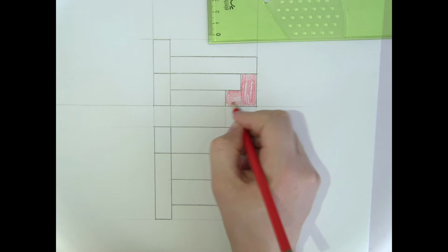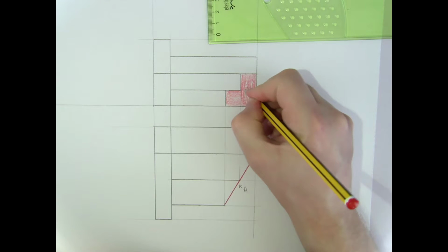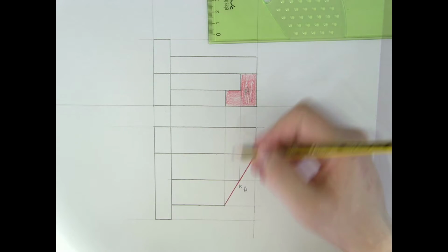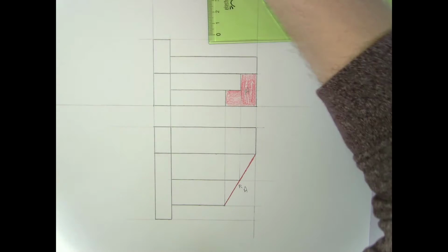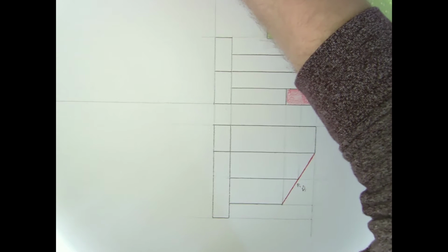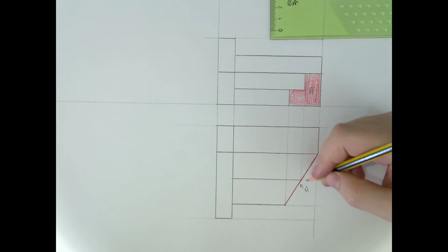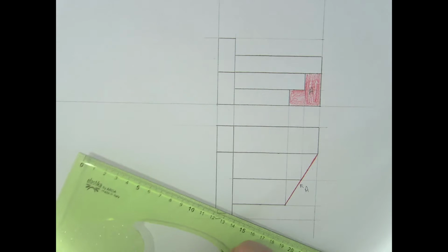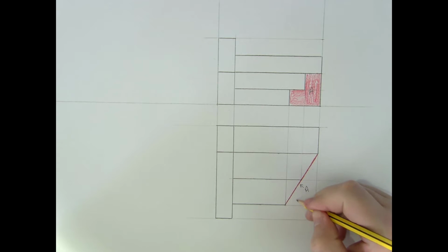But in our auxiliary, it's the true shape of the structure, so it's the whole thing that we need to draw the true shape of. So that's surface A, and this is an edge view of surface A. So for the next part of this, we're going to look at drawing the auxiliary view. And the auxiliary view is projected. To find an auxiliary, you need to look in perpendicular to the edge, and the edge that we're operating off of is at 60 degrees to the horizontal. 30 degrees to here, 60 degrees to the horizontal.